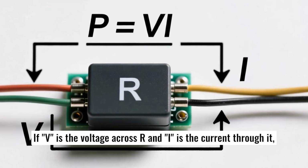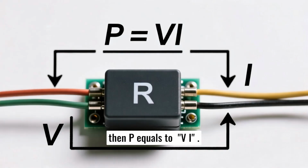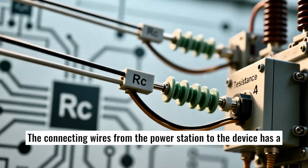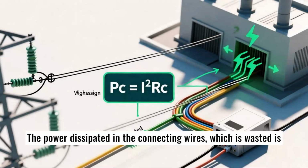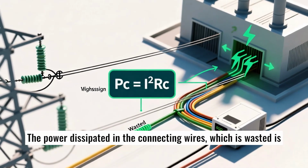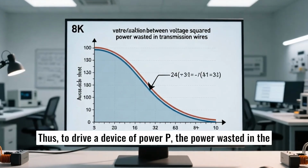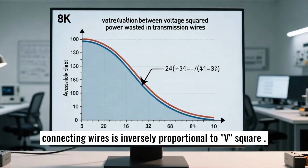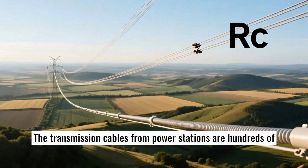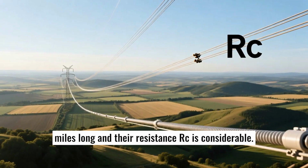If V is the voltage across R and I is the current through it, then P equals VI. The connecting wires from the power station to the device have a finite resistance, RC. The power dissipated in the connecting wires, which is wasted, is PC, with PC equals I squared multiplied by RC. Thus, to drive a device of power P, the power wasted in the connecting wires is inversely proportional to V squared. The transmission cables from power stations are hundreds of miles long, and their resistance RC is considerable.